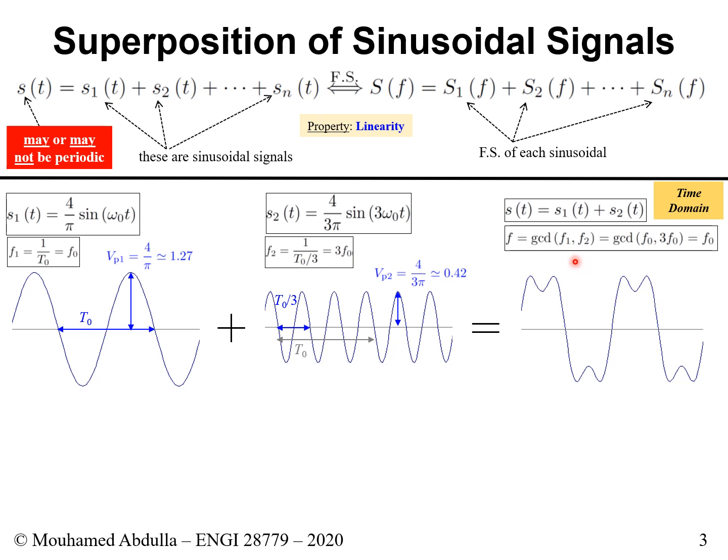Sometimes you might do the GCD of 2 sinusoidals and you won't get anything. You won't be able to solve it. The GCD will not give you a result. If you don't get a result, it means that the addition of 2 sinusoidals does not result in a periodic signal. This is why I put it in red here. Sometimes it is periodic, sometimes it is not. You really have to prove whether it is periodic or not. In this case, we kind of knew it was going to be periodic because inside the sinusoidal, it's already represented in terms of the fundamental frequency omega naught. So we kind of knew it's going to be periodic.